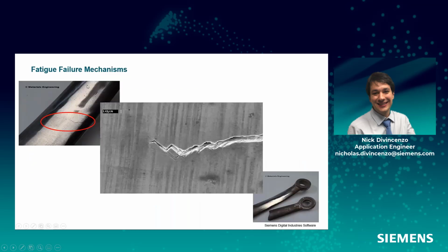The mechanism for fatigue is the onset and propagation of tiny cracks in the metallic specimen. We've got an image here of a crack forming in a material, a nice blown up image of that same bar, where we can see that there's a point where a crack initiates, and this is typically caused by irregularities or imperfections in the material that's being used. So there might be, due to the manufacturing process of the material, some local stress concentrations already.